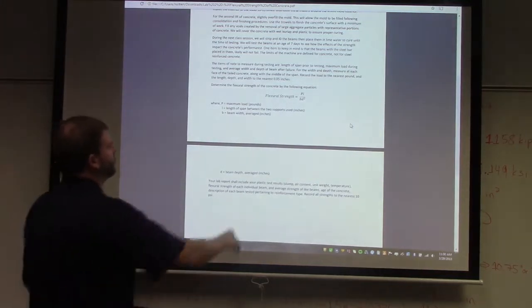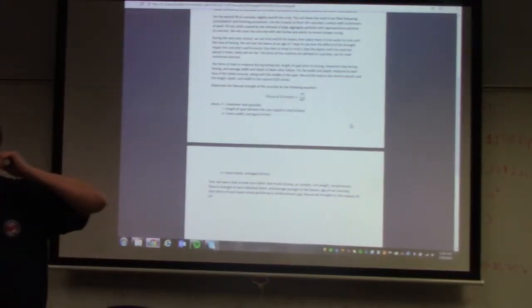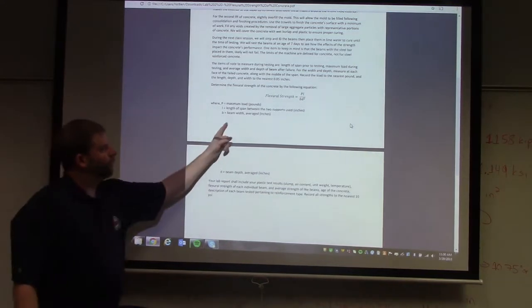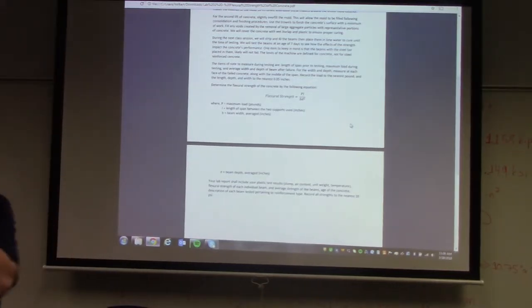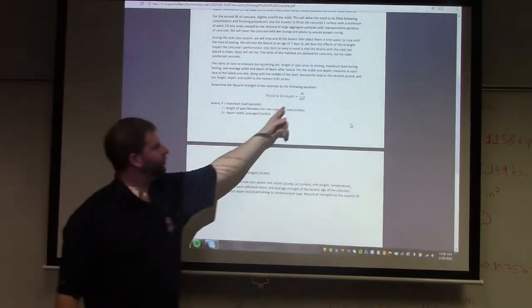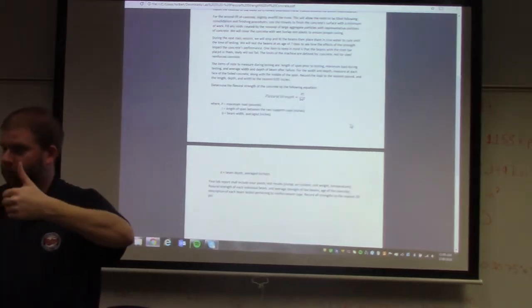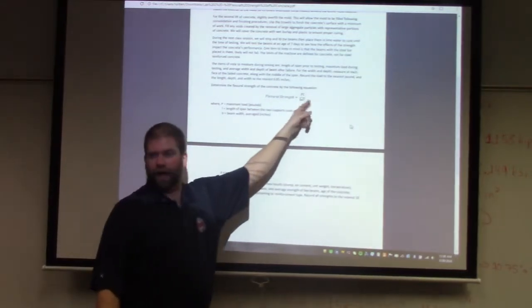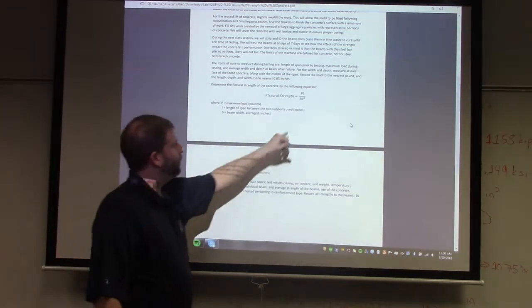Yeah, so then in your calculation, your average beam width will be B, but again, remember, it's going to be the average of the 3, just like the depth is going to be the average of the 3. Okay? When we look at this, what's our units of flexural strength? What's our units of P? Our load? Pounds? Could be kips, right? Kips or pounds. What's our units on L? Inches. Okay, so we have pound inches. What's our units on B?